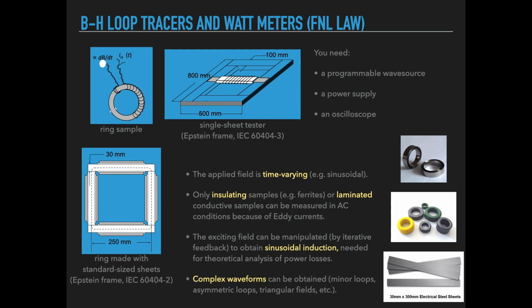In any case, in order to exploit the Faraday-Neumann-Lenz law, the measurement is done in a time-varying condition, meaning that the magnetic field is generated normally by a set of coils that are powered by a sinusoidal current, generating a sinusoidal magnetic field. Another set of coils, called pickup coils, are wound around the sample or a portion of the sample and detect the electromotive force generated by the variation of the flux due to the variation of the magnetization of the sample that is submitted to the sinusoidal magnetic field.